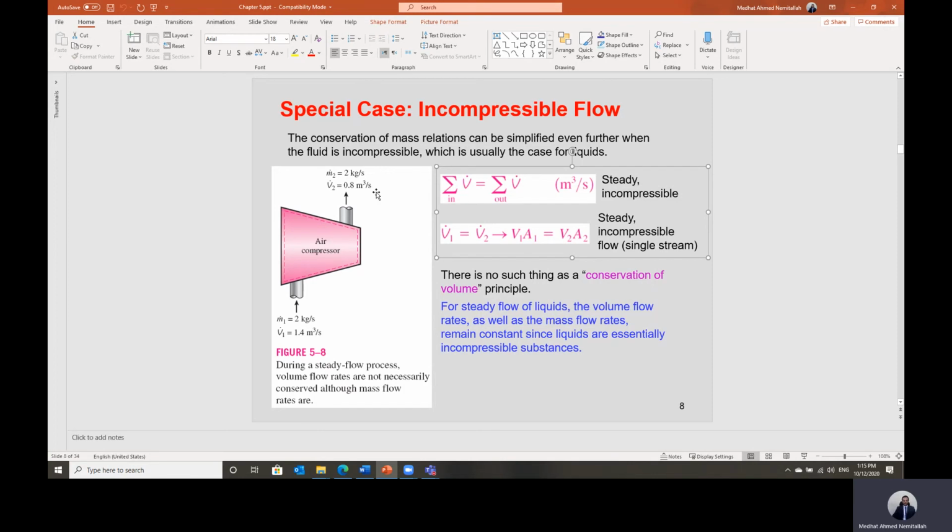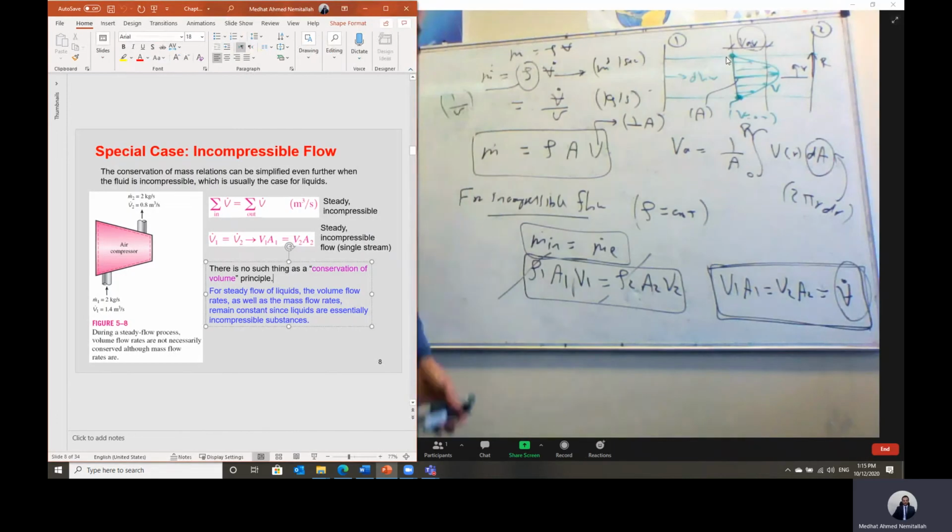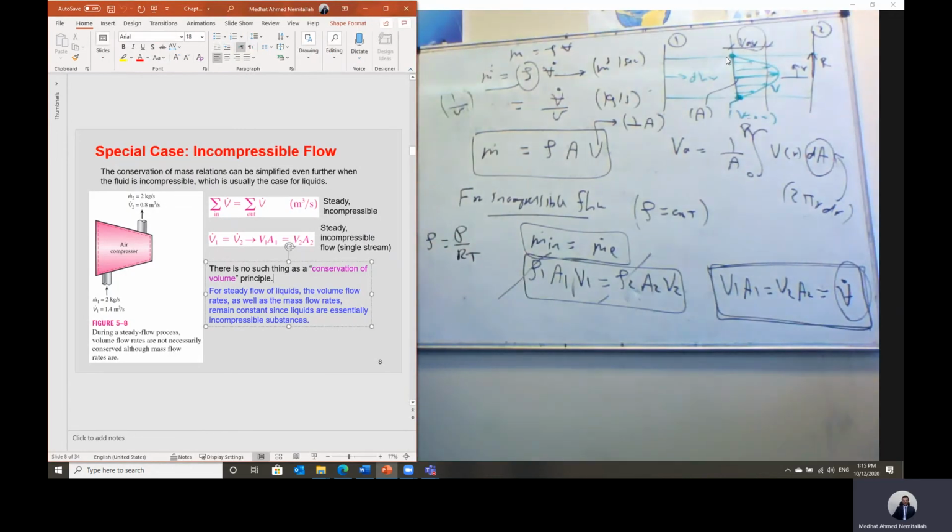But in case of compressible flow, like gases, liquid is incompressible but gas is compressible, like when we have a compressor that takes air and its function is to raise its pressure. So in this case, density for gases, density is equal to what, Shabab? Density for gases is equal to P divided by RT, as we have Pv equal to RT. Specific volume v is 1 over density. So density will equal pressure divided by RT.